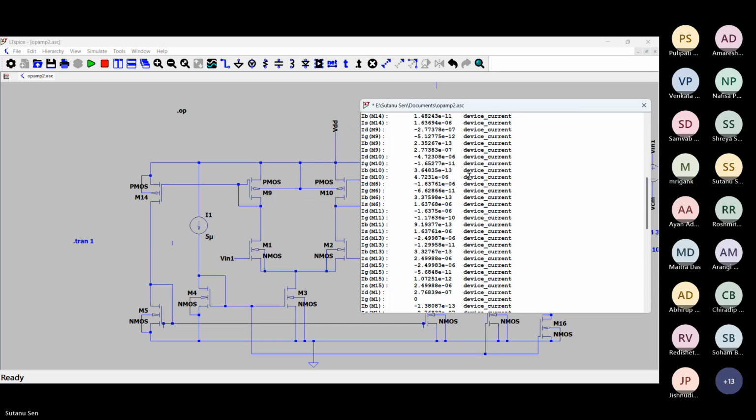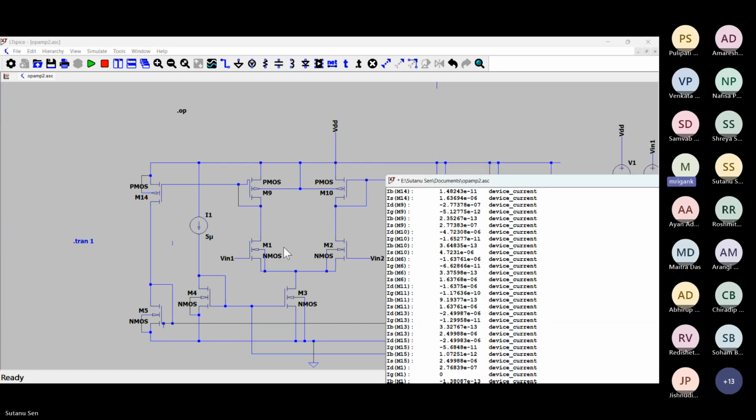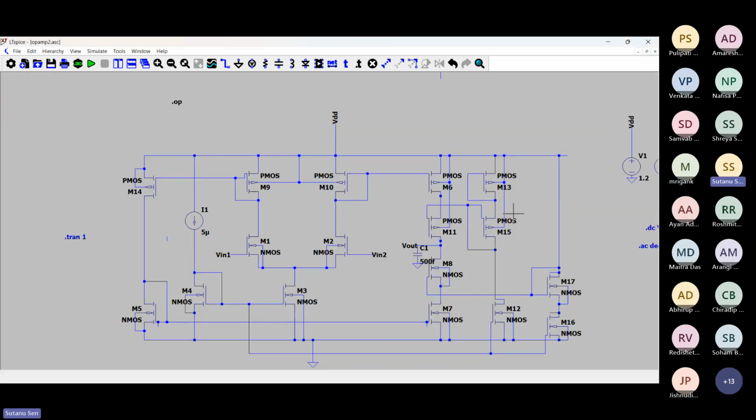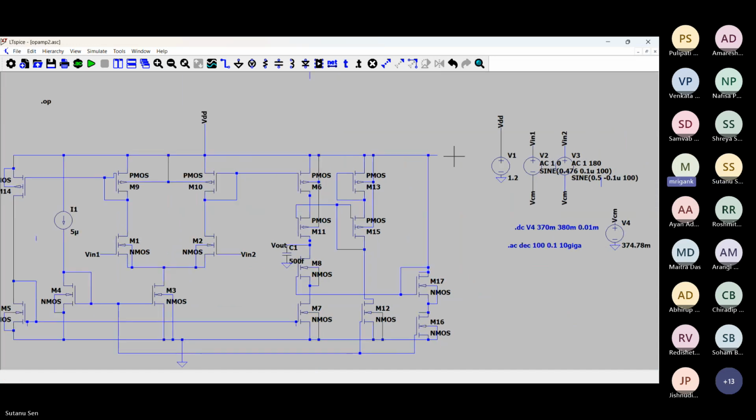And that is not good actually, because this will also mean that you're going to get a good amount of common mode gain. What you can do is just try to apply the signal you have applied to the gate of M2 or M1. Sir, I have applied it at the gate of both, like V1, V2. What you will do is just apply it at the gate of M1 only and see what the situation is. Yes, sir. So I'll put M2 at DC bias, right? Yes.